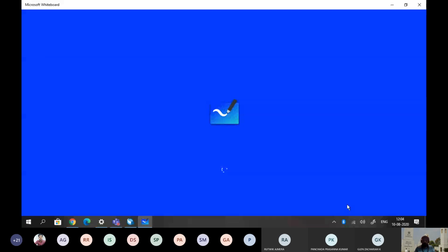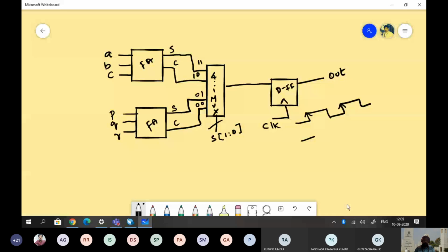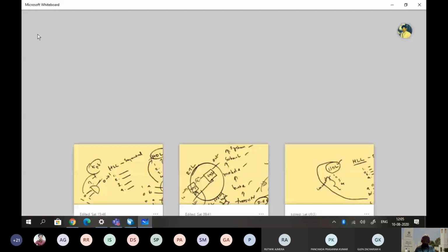In this example, we are going to manually force the IOs. Where you need to write the test bench that will generate whatever the symbols you want to run, for that we have to use ModelSim only. Okay, sir.